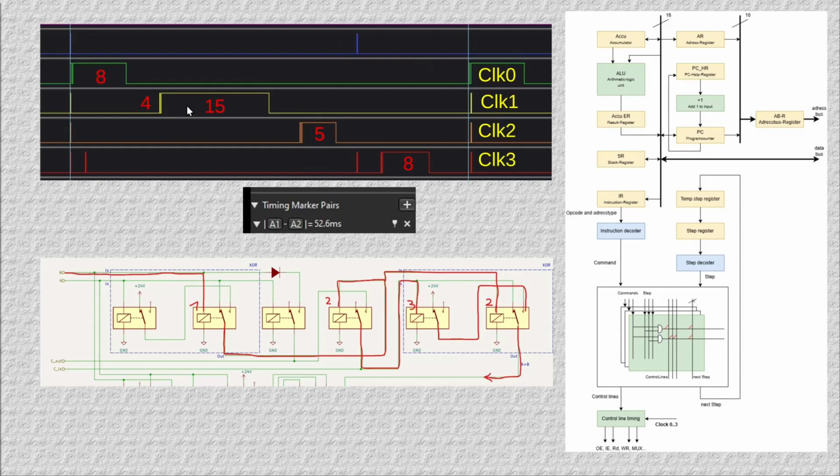So 12 milliseconds are too fast for the 50 millisecond chain we have here. And I am 95% sure that this is the reason why in the following short video the division function is not crashing, but we have the wrong result in the accumulator after the function.